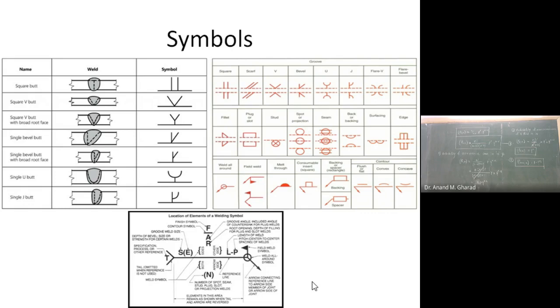This is true for bolts. Just as bolts have different diameters, for any connection you will be representing the arrow, and on that arrow you will be showing the size. That is, if it is 16 mm diameter, you will just write 16. That's it. The rest will be understood because you will mention on the drawing sheet that all the units are in mm. Then all the numbers you represent will automatically be assigned to the mm unit, and so on.